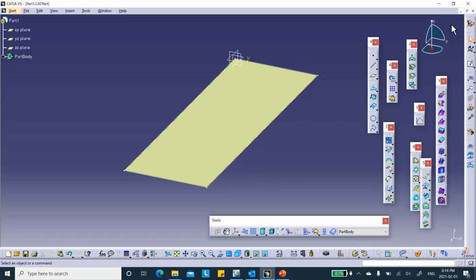Okay, now we're going to go to, oh yeah, we can create a rosette here, but I'll do that later because you can create a coordinate system here, there's no problem, and then use it as a rosette later on. Even if you forgot, in the next step, when you go to the composite design, you can create a rosette on the fly. So that's what I'm going to do, okay? So I'm going to click on